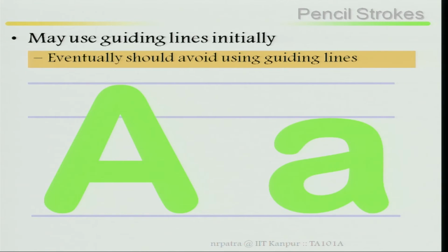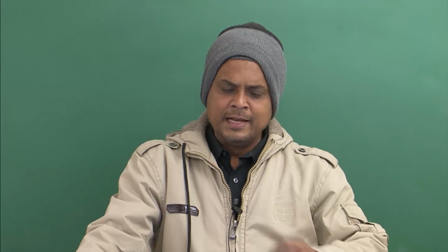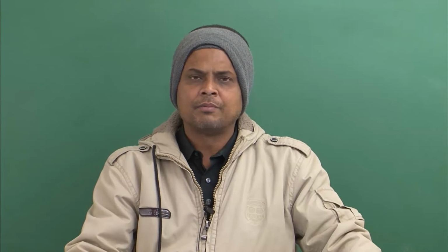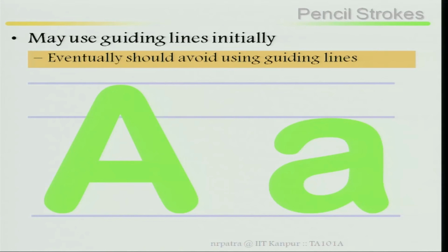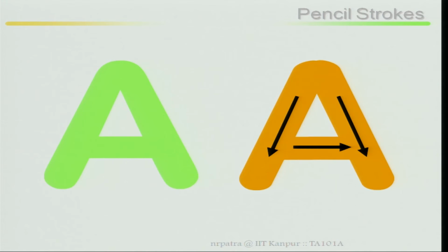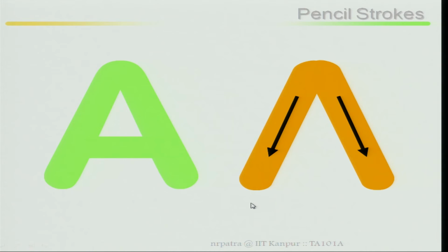Then we will start one by one. These are all general guidelines. Once you write your name, roll number, or any write-up by pencil, you have to use lettering with proper strokes. Suppose this is capital A and this is small a. How am I going to write capital A? Look at the sequence. This is my first stroke, second stroke, then this will be your third stroke.